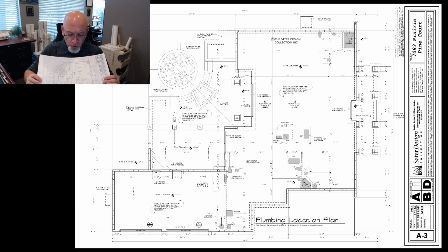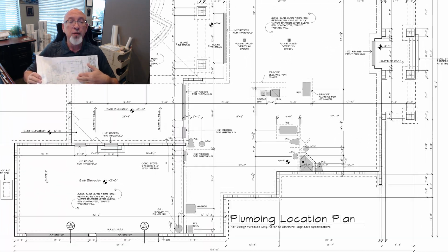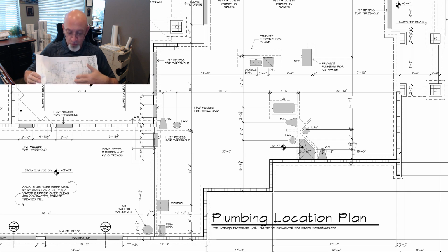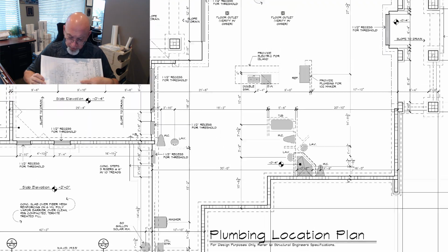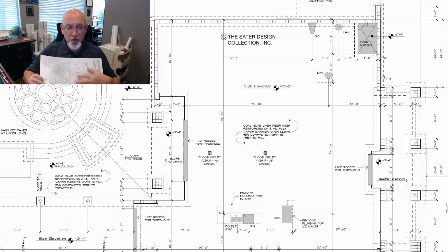It gives the overall dimensions and it gives the location of where the plumbing is, so your plumber can locate if he's running some plumbing lines, like especially in a condition where it's a slab floor system where you'd have to pre-plumb all this beforehand before pouring the slab. So it's important to know exactly where the plumbing stacks are located, drains, etc. So it gives some general information for that, what the elevations of the slabs are of floor systems.